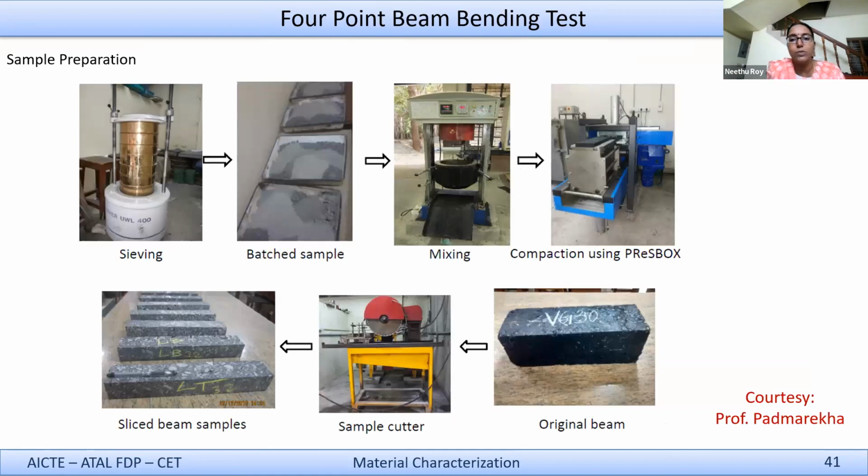So this is the specimen preparation. I've taken this from Dr. Padmarekha. You have the sieving, the batching, then the mixing. You compact the specimen in a press box, and then you get an original beam which can be sliced according to the required specimen. And these are your sliced specimens.